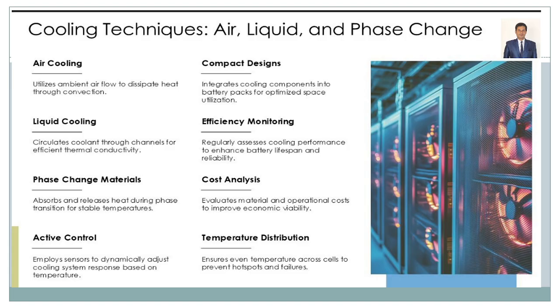Next we have liquid cooling. In liquid cooling there is circulation, with coolant channels for the cooling effect. That is what I told about especially in BTMS. Most BTMS use a cooling system where coolant cools all the individual cells. They use liquid or other fluids to cool each individual cell, so that reduces your thermal load.